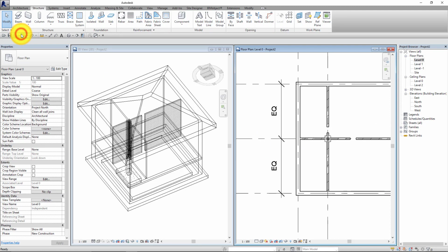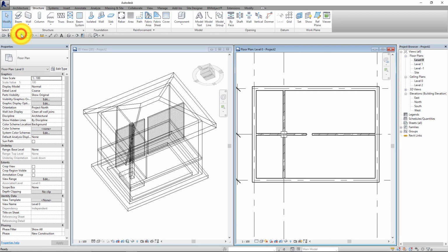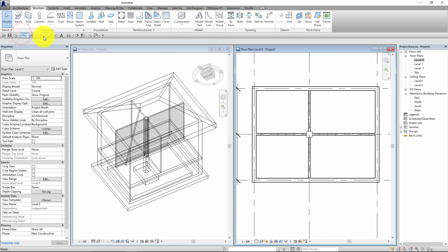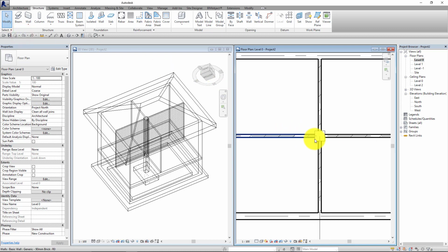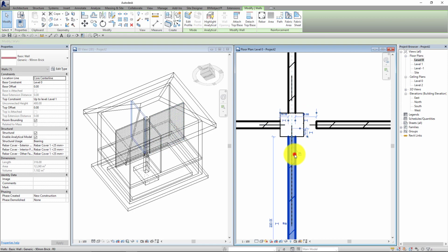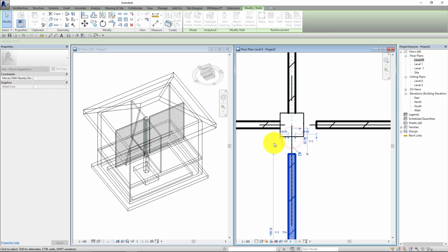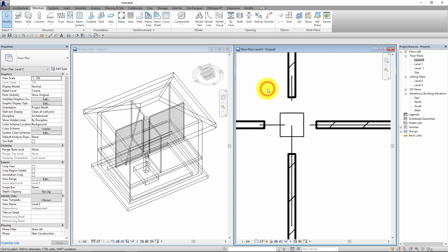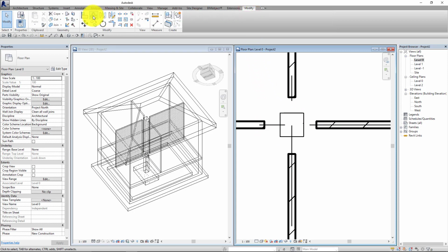Please also remember to use the 3D view, because you can see how the level and the building is changing. Please select one wall and then try to click the blue button, and then move the ending of the wall. Please go to the modify panel and then use the align tool and then try to connect the column with the wall.